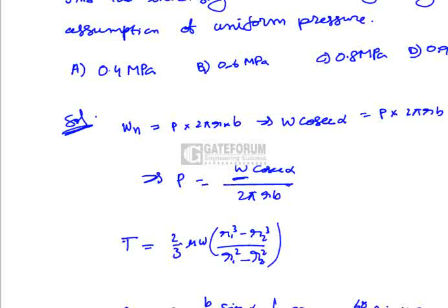In the same way, the inner radius of the clutch is given by R minus B by 2 sin alpha, which is nearly equal to 154 mm. Now substitute all these values in the torque equation, where mu is the coefficient of friction and is given as 0.26. So by using all these, we can calculate W.